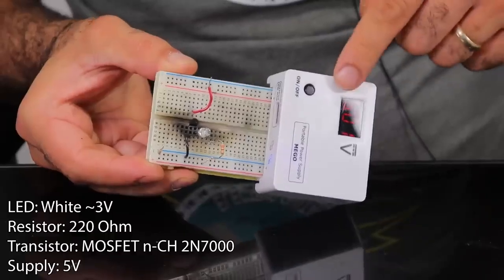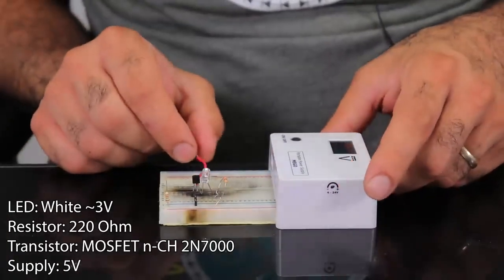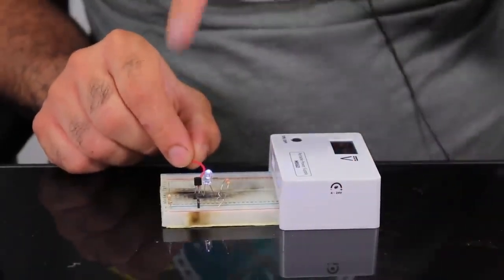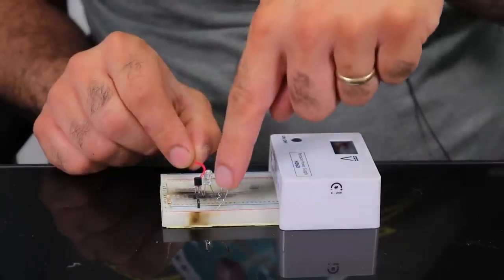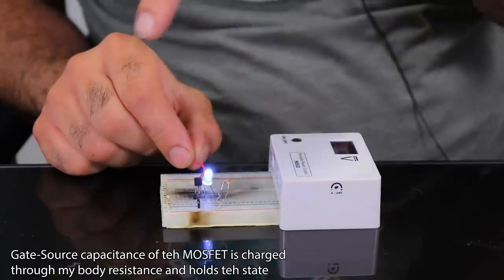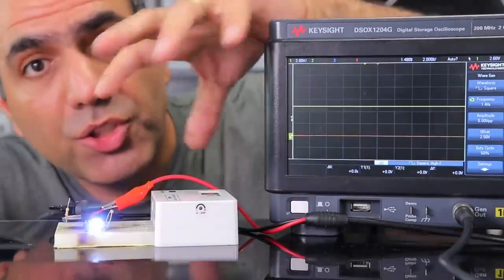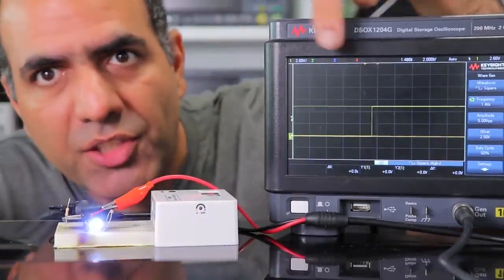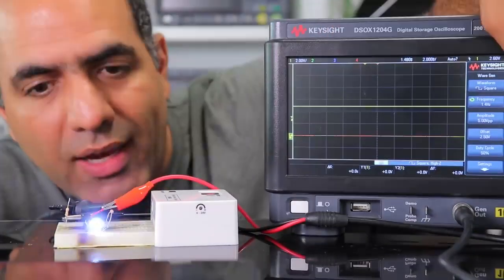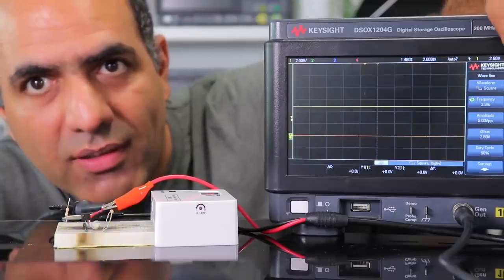Here's my 5 volt supply and the circuit here. Don't mind the burned breadboard. I'm using a MOSFET, so if I hold the gate and touch the 5 volt, bing, the LED turns on, and touch the ground, it turns off. Bing, bong, bing, bong. Of course, we can use a microcontroller to drive the LED, but here I'm using a function generator. Now let's see what happens when I increase the frequency.